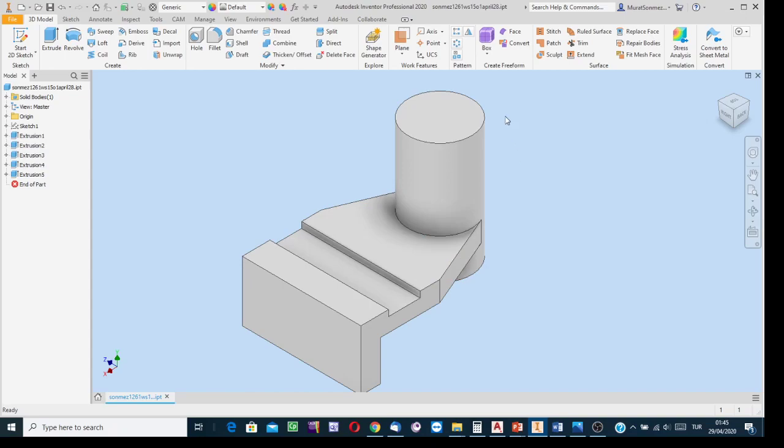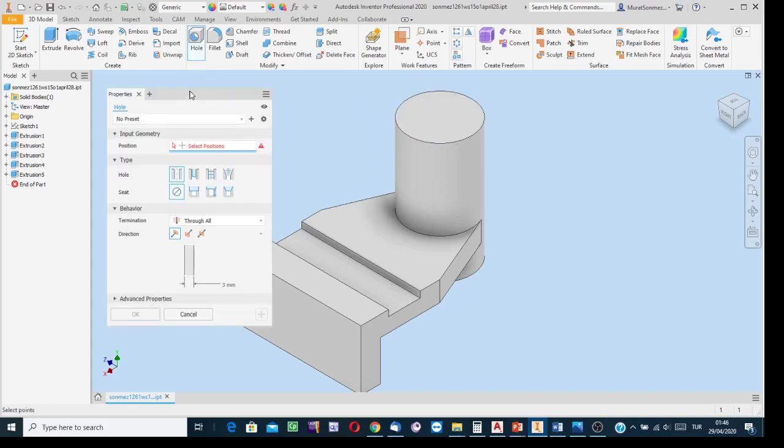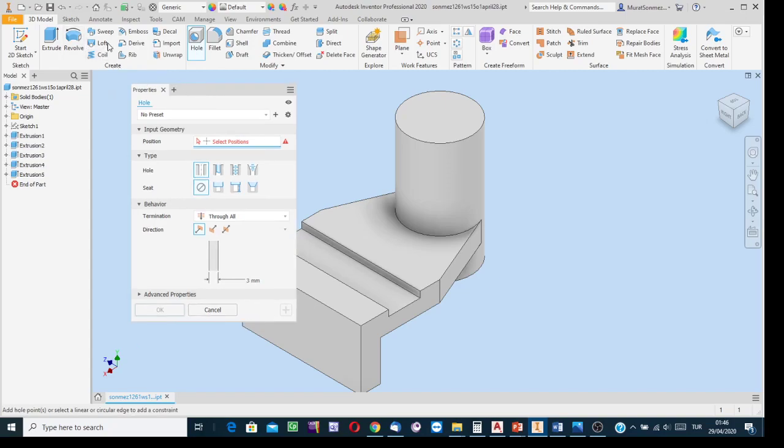One more time apply cutting, but it is for hole creation. For creating the holes, we have a special tool, the hole creation tool. No need to draw a sketch if the edge of the hole is over a flat surface. Just start the process with a click. Extrusion process, revolve process, sweep, loft require fresh sketches. But the hole process does not require one, of course, if the edge of the hole is over a flat surface.